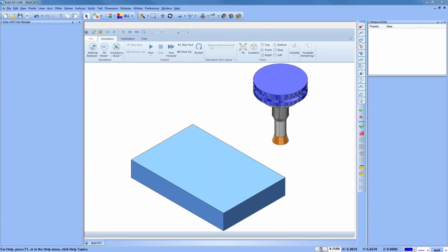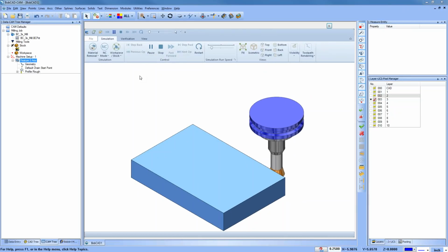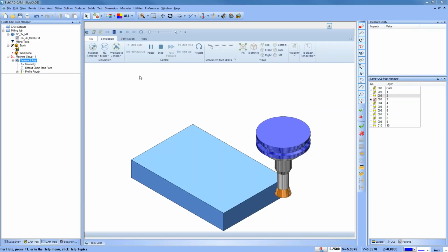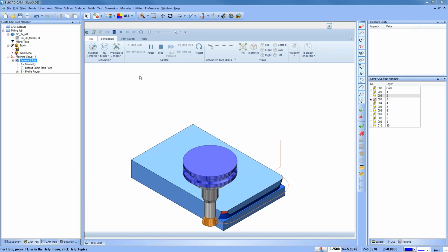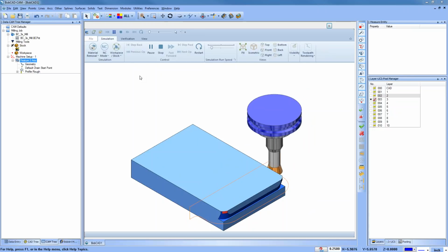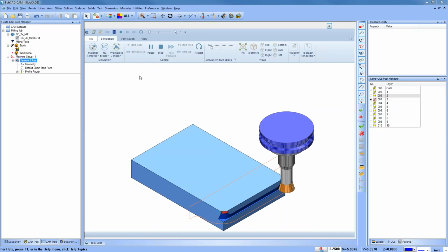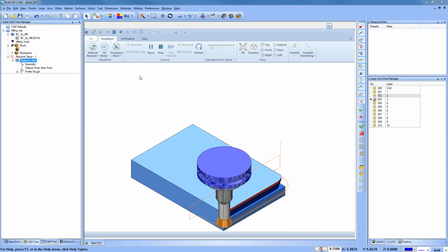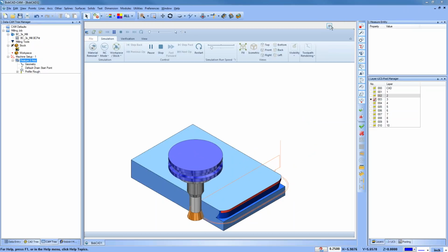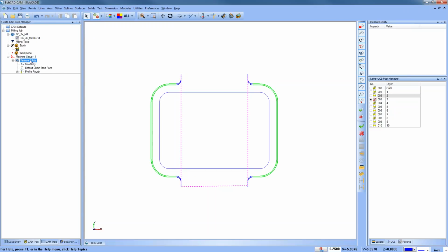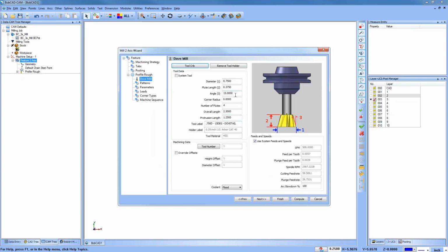Okay, so by walking the tool into the profile, instead of it taking one more aggressive cut, what you're going to end up with is 2 cuts or 3 cuts or however many you put in there. Okay, so you can see it took the 1st pass, and then now it's taking the 2nd pass here. Let me make some adjustments here. Let's edit this tool, let's see here, diameter, flute length, angle. And it doesn't look like I have a shank diameter in this one.